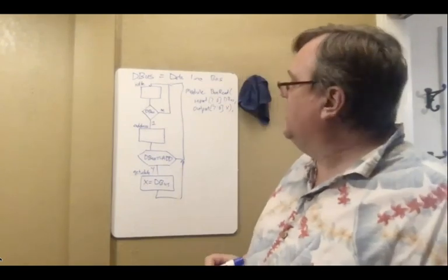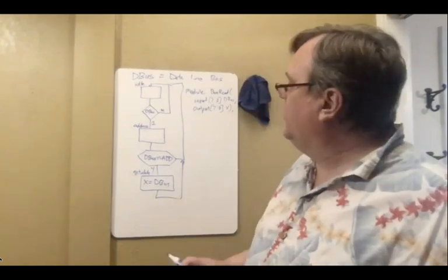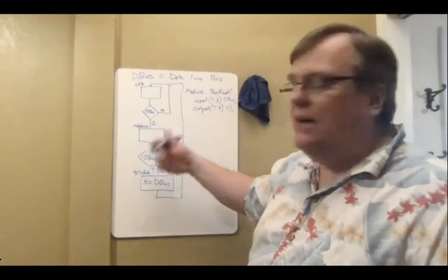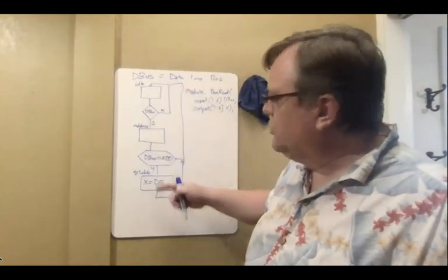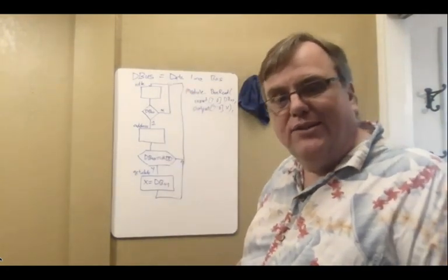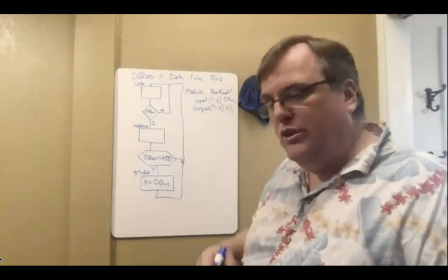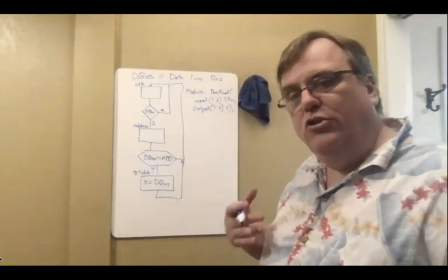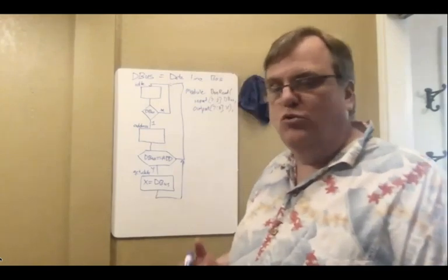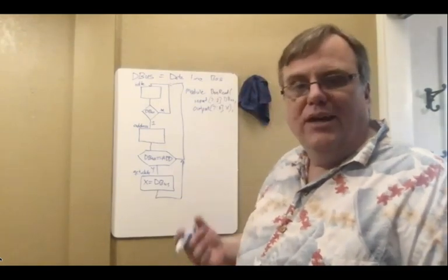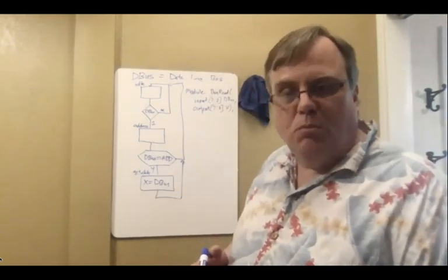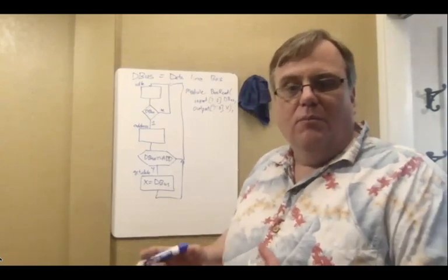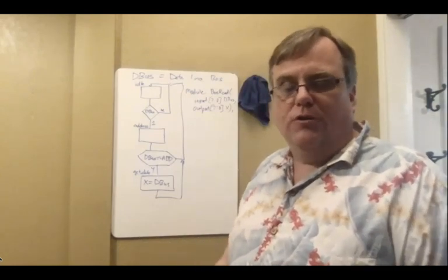Now I can look and say, what are the internal variables that I need? Well, internally, I need to have a state to track which one of these. So I've got to determine, do I want to use binary? Do I want to use gray code? Do I want to use one hot? Let's say I want something very small, but I do worry about errors on flipping.